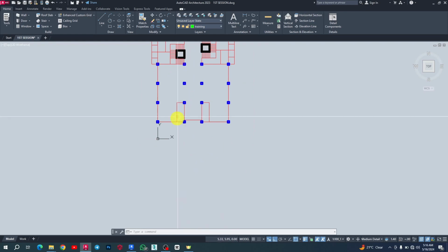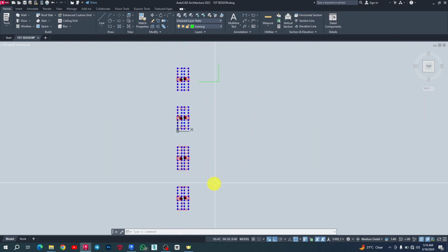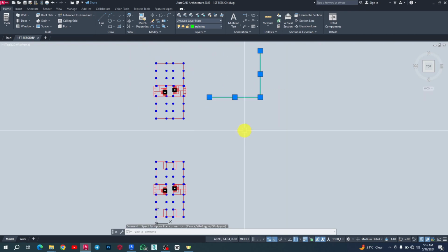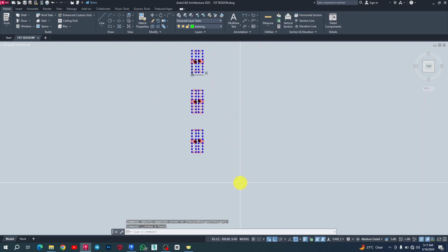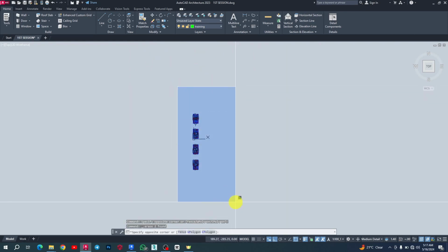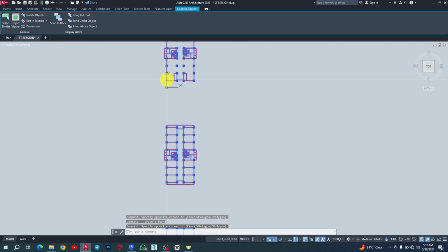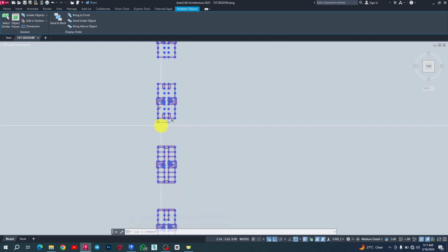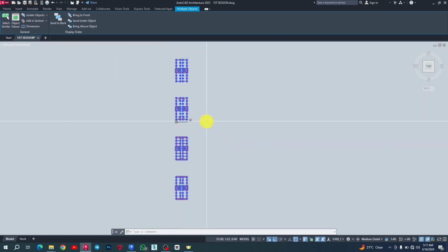I'm going to now go straight into exporting this into Revit. Okay, so I explained this drawing yesterday. I'm going to delete this, and something to note is that you want to choose an origin for your drawing. Since they are both Autodesk software, it's always good for you to have a common origin, right? Because Revit will want to pick the same origin you're exporting from AutoCAD with.